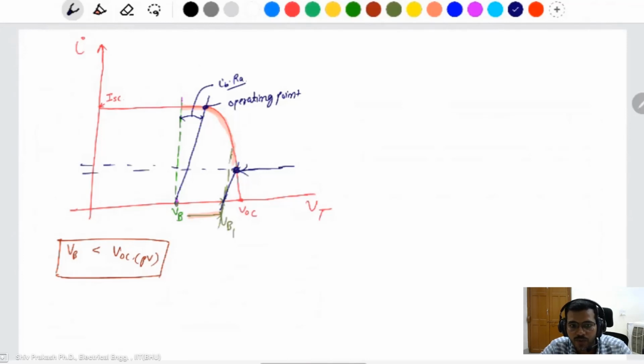It means if you go towards the fully charged battery, towards 100% SOC, the battery voltage increases and the current decreases. In the case of a solar panel, the current will decrease. That's why this is the perfect charger for the battery in direct connection. If a battery is connected to the solar panel, the current will be reduced, and the error between the actual battery voltage and the terminal voltage will be minimized.